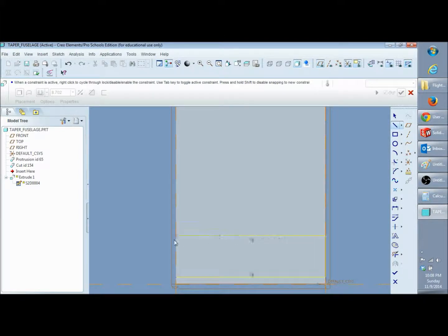So this block would represent the space between each of your ribs, whereas this little gap right here, where there is actually no enclosed space, by that I mean within the lines, represents where your rib is going to be. 0.125, which is the thickness of most sheets of wood that you might end up using.